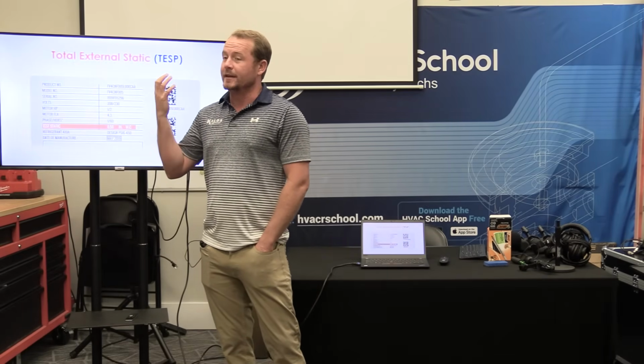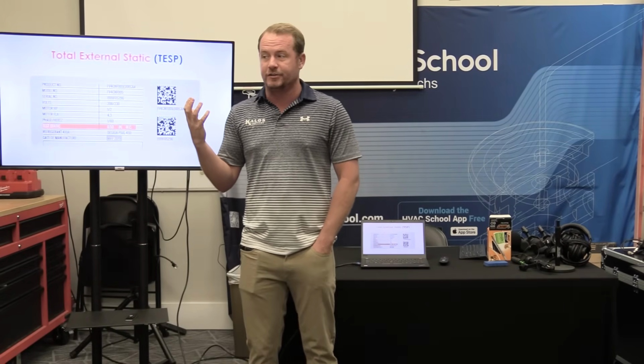A lot of times, these consistent motor module failures that we see on certain systems, a lot of times it has to do with static pressure, which is why when we do a motor module replacement, when we get done with that, because obviously you can't test static pressure until you replace the module, you should definitely check the static pressure. Now let's be practical about this. Can the static pressure that the blower motor sees change over time? So you install a system and it's one thing, over time it changes, right?